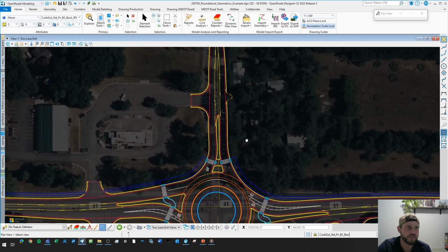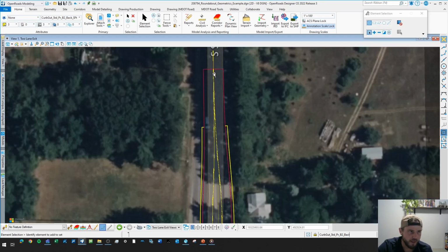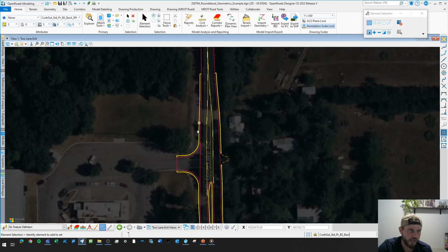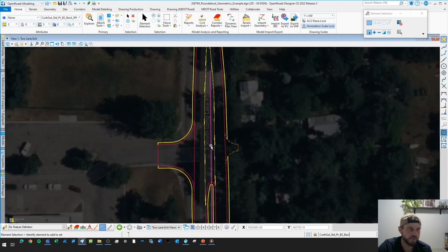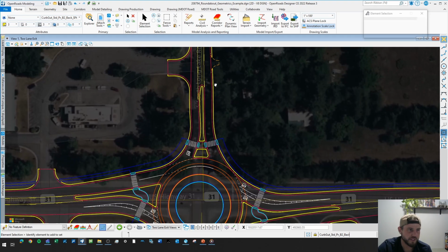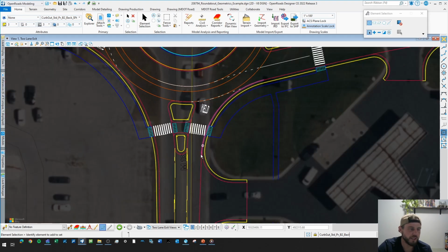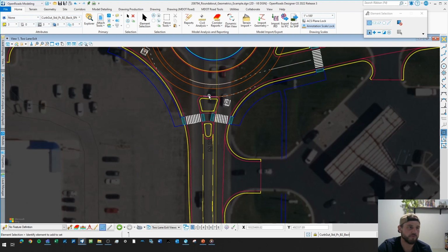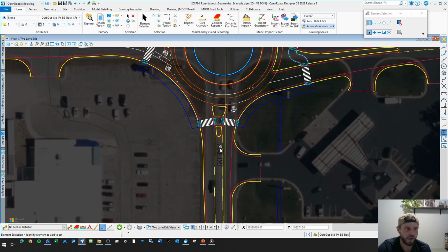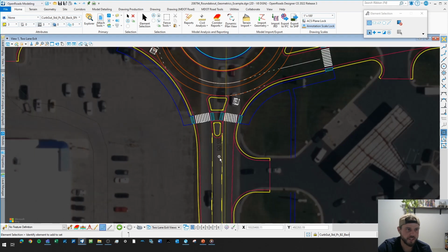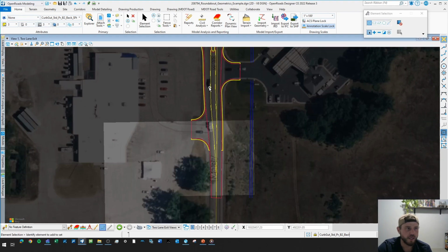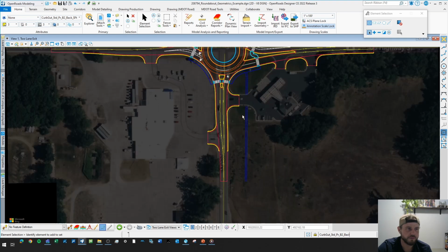So you have single lanes going this way. Just took some radii and curved it out. We wanted to have a center left turn lane for this, so that we could pop off right after and take a left in there. And this one ended up being a shorter nose, 50-foot minimum. So this is exactly at 50 feet, and that would allow traffic to hop in this lane and take that left turn before we kill that off coming down here.